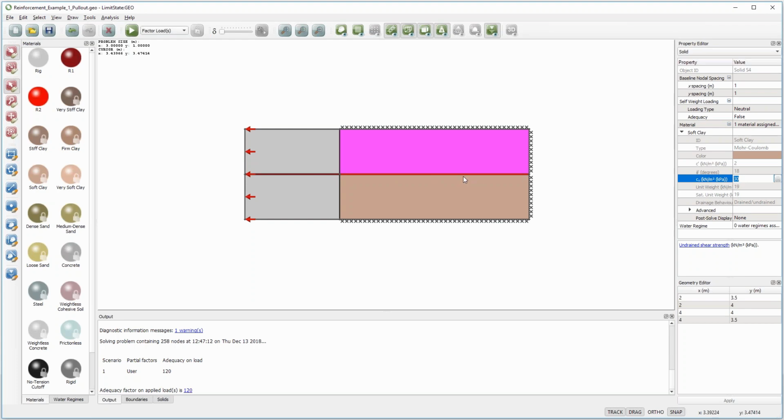If this reinforcement were actually a plane, that is the force required to pull it out. If we had hundreds of nails all adjacent to each other so that we formed a plane, the maximum force that we can pull out is the shear strength of 30 times 2, because we've got it above and below, multiplied by the length of 2 there, which comes out as 120. So physically we cannot get any more pull out than 120 from that soil, even if we had contiguous soil nails all the way along. So that's why the software is giving us that answer.